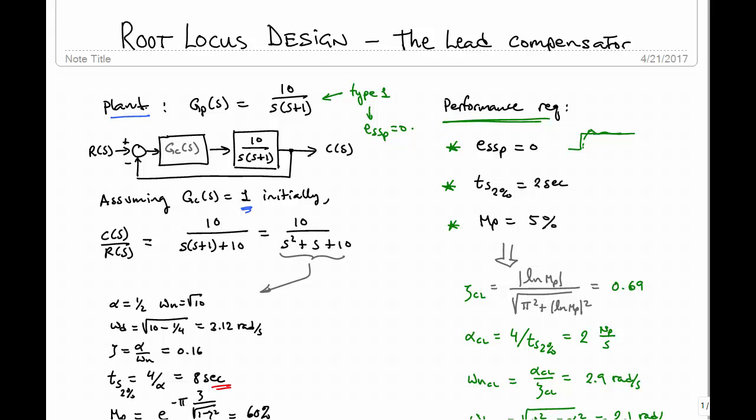It will have a constant steady state error due to a ramp, but our specification doesn't say anything about steady state velocity error requirements. So our system does meet the steady state position error. That's good. We don't have to make any adjustments or add any compensation to achieve that. Even our uncompensated system would achieve a 0 steady state error.